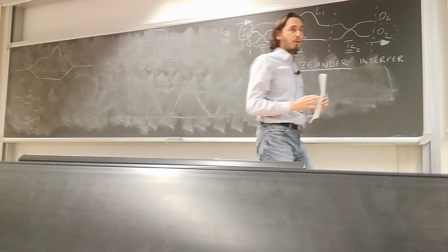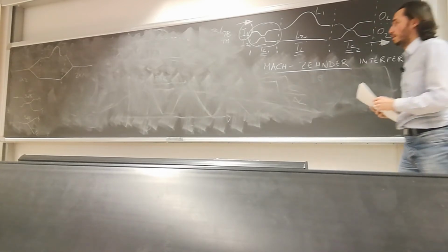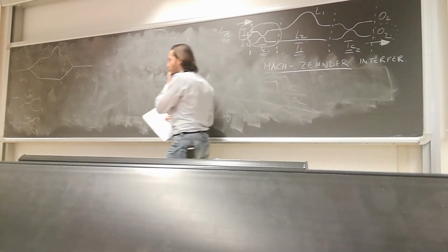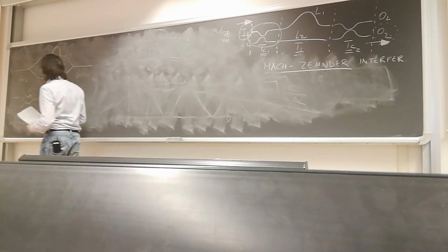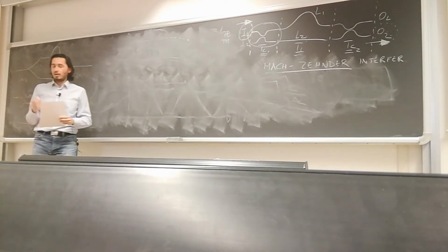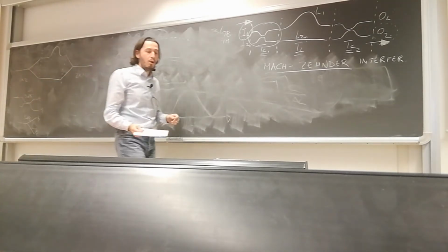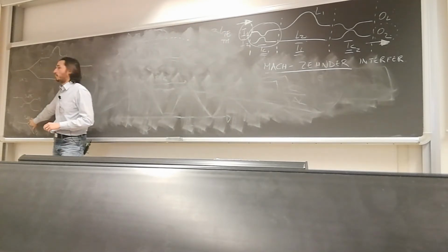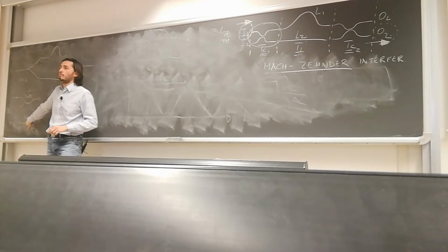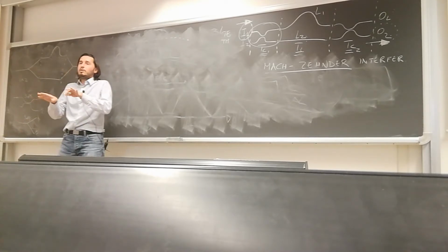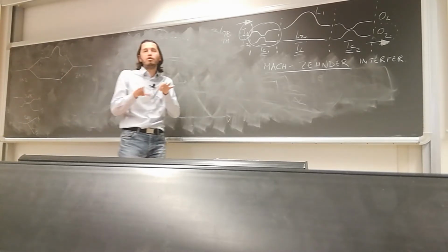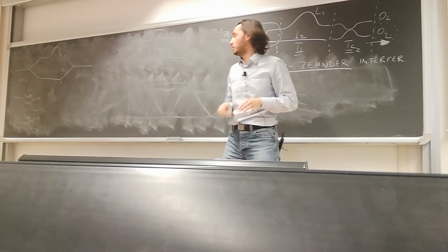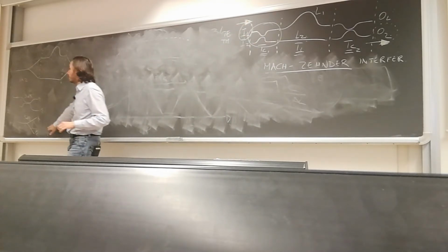This is a good point. The wavelength dependence is expected to be different, and typically, if I want a lower wavelength dependence, this could be preferable because the split ratio 50-50, because of the symmetry of the structure, is maintained. If you change the frequency, maybe what is going to happen here is some additional loss.